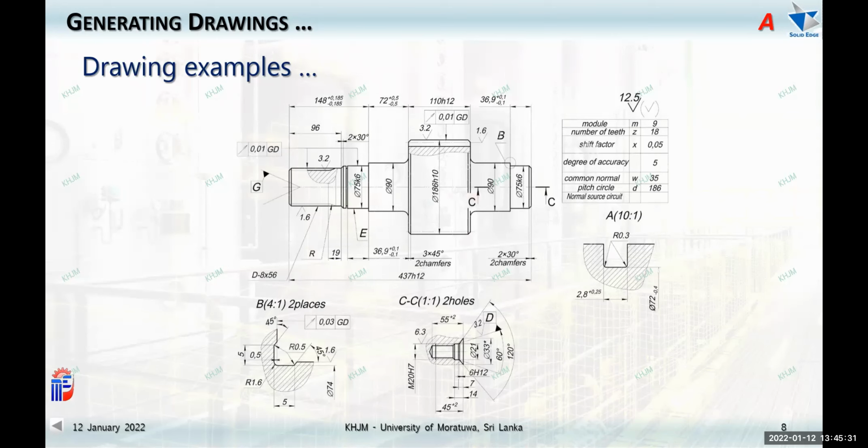I don't know whether you have gone through these things in the manufacturing lectures, but we need to use these two charts. You are using the same thing, someone else will also use the same thing. So you can interpret how much precision should be required for this particular part, and then what kind of a machine that I should use. Tolerance means the variations. Within this, your diameter should stay. And in some other places, you don't have it because it's not that critical. So those things are not that critical.